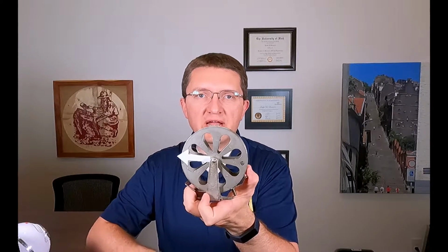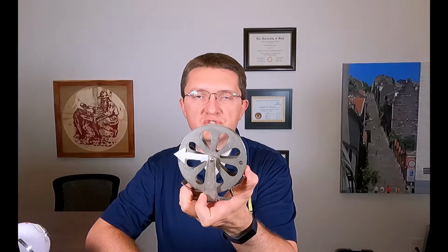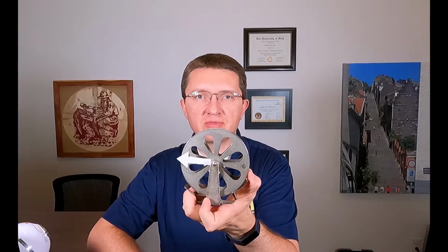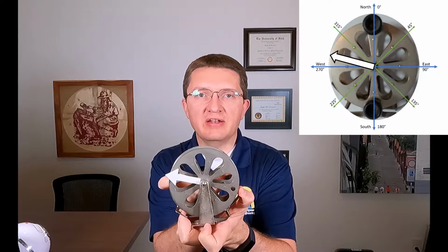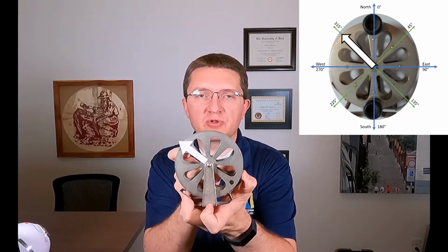The first two we're going to talk about are Rotate Absolute and Rotate Relative. They're very similar, but we have to discuss those terms. So for this example, let's say my arrow is facing west, which is 270 degrees. And I say, let's rotate relative 45 degrees. It's going to go from where it's at and add 45 degrees and go to 315 degrees.